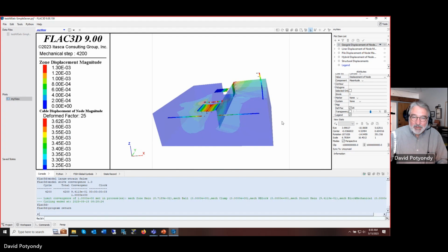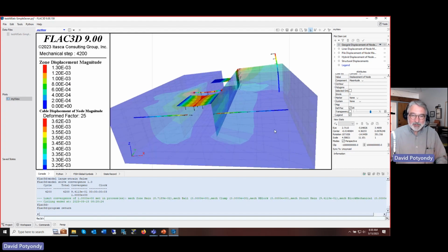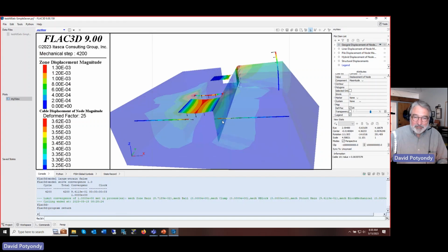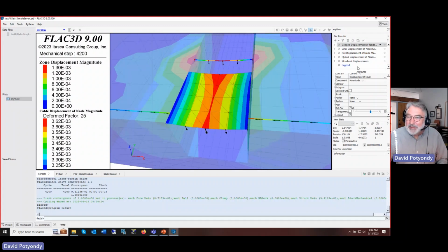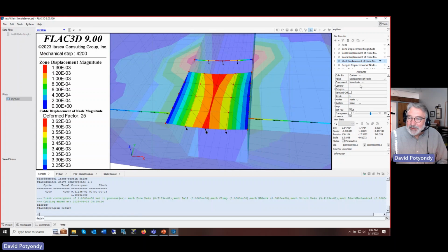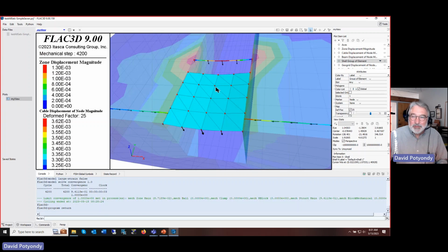Okay. While we're talking about this, before we talk about putting on the properties, let's look at a couple other things here. Let's zoom in on this shell structure. So I've got a shell plot item, and we can look at the nodes. So it says marker. I'm going to say node, and instead of drawing a contour, I'm going to say label group. So there's the nodes. I can make them bigger and smaller. I say marker node size 3, 4, 5, 6, 7, etc.